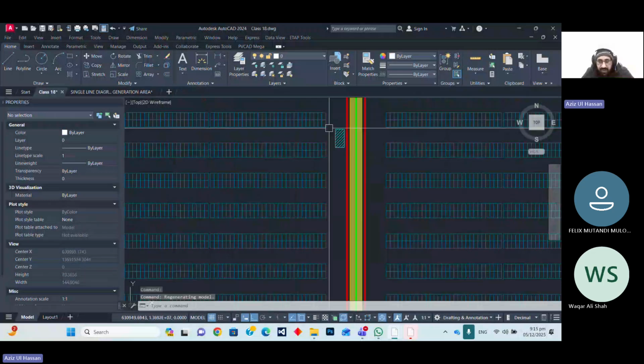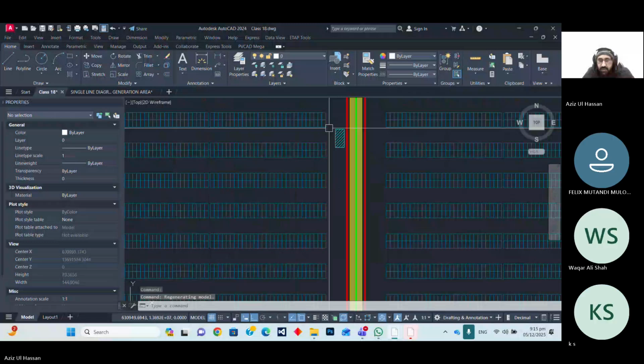So we have to combine these MV stations, the string inverters connected to these MV stations, switchgear, and then from switchgear to the MV station, the transformer, and then transformer to the MV switchgear. From this MV station, the output goes to the switching station, the POC, point of connection. So this is basically how we will connect our loop there.